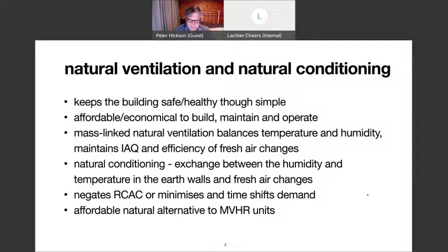The importance and extent of sealing is also related to climate and design intent. Sealing is yet less useful in massive buildings using natural conditioning and in buildings that rely on constant natural ventilation. Air tightness introduces a number of health and safety concerns, so that mechanical ventilation becomes necessary. Relying on sealing and insulation for energy efficiency in effectively lightweight buildings leads to overheating and dependence on air conditioning and mechanical ventilation.